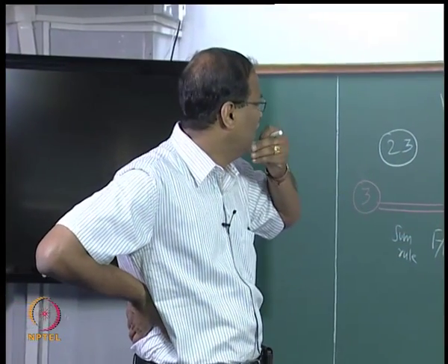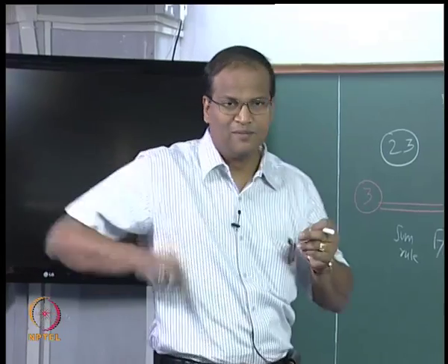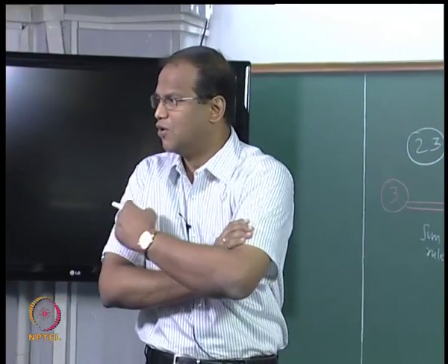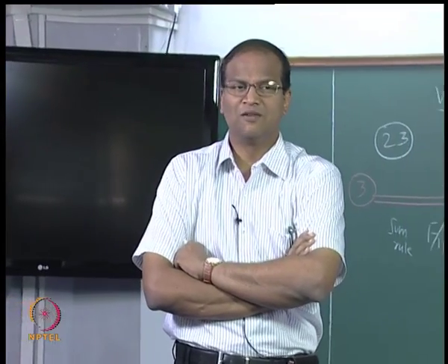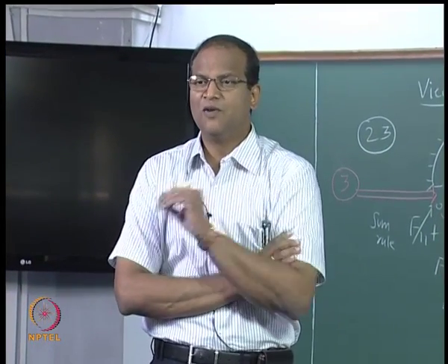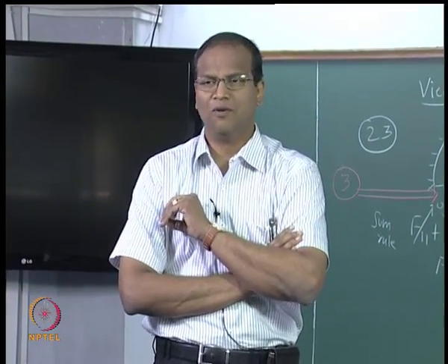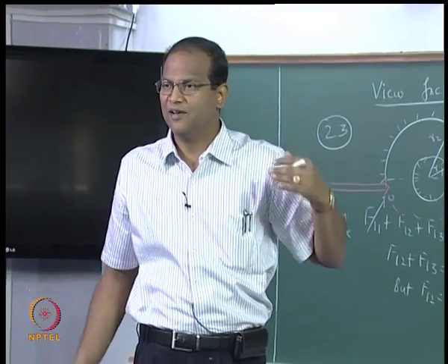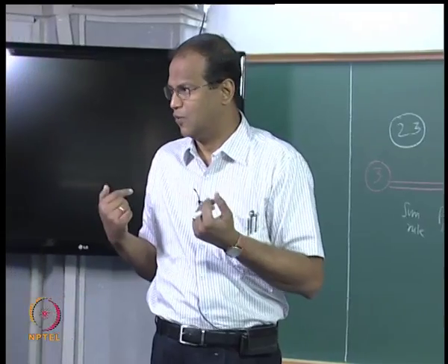Now there should be some way: you have to take cos theta i, cos theta j, dAi, dAj, and you have to integrate by contour integration, and you can get it. Of course there are some asymptotic limits. When r1 is very small compared to r2, then we can make some limiting assumptions, then f2 to itself will be equal to 1 and so on.